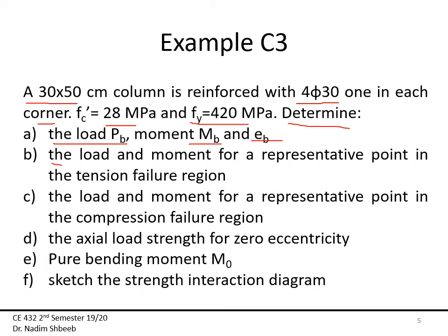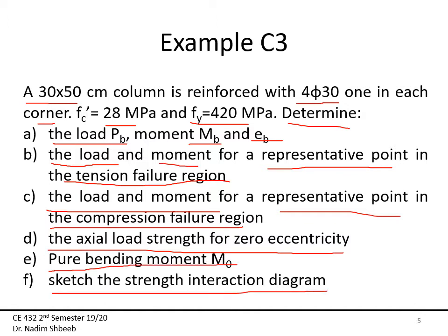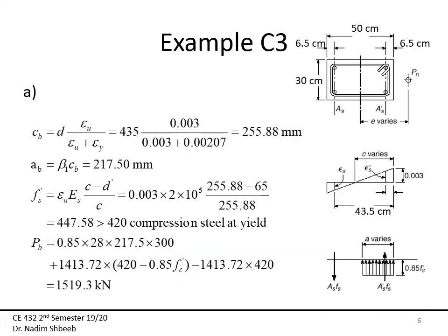The second requirement, I would like to know the load and moment for a representative point in the tension failure region. Third requirement is the load and moment for a representative point in the compression failure region. I would like you to find the axial load strength for zero eccentricity. I would also like you to find the pure bending moment M0, and then I want you to sketch the strength interaction diagram. Okay, so let's start with the first requirement, finding the balance force.